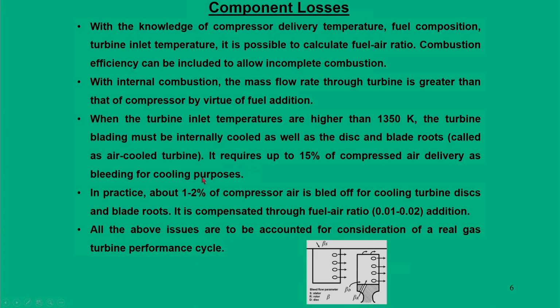Apart from that, to quantify specific fuel consumption, we also have to assume some combustion efficiency. That means fuel has certain energy which we call the calorific value. The entire calorific value of the fuel is not recovered; almost 98 or 99% of the fuel gets combusted. So, by assuming a combustion efficiency, we allow for incomplete combustion. This is also a part of component losses.